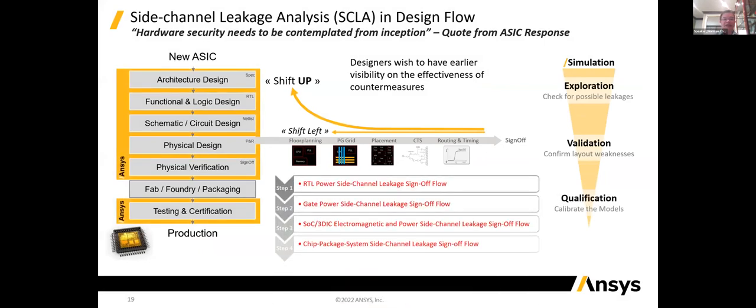So one ask from the security designers is that they want to see the solution earlier. During the RTL and gate-level design, if we can provide feedback on where there is potential leakage for the side channel, they can fix the problem. They don't need to wait until tape-out and the measurement lab, where certification cannot pass and then there will be a delay of 3 to 6 months. That includes the EM side channel, power noise side channel, and also the chip-package-system side channel simulation.